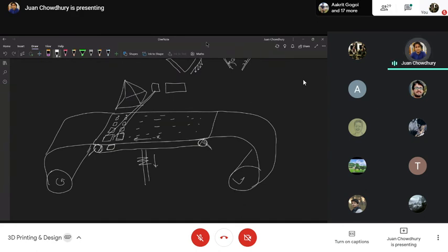We will be aligning these two parts, and again it will be moved up, it will fix it, and then it will move down. As you repetitively do this process, you will stack laminas one after another, eventually leading to the prism structure that you were originally willing to make.